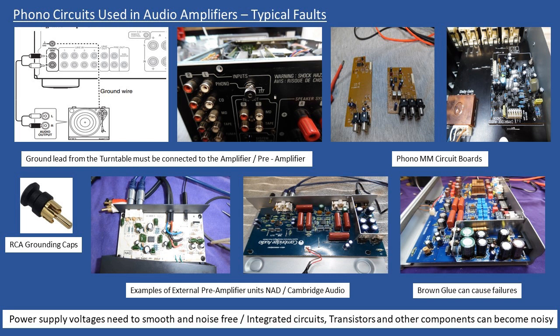And then if it's none of those faults, you have this sort of crackling sound, then you're normally looking at a component which has gone noisy. And as we mentioned, it could be a transistor, it could be a capacitor, it could be a diode, it could be one of these integrated circuits. For the many years that I've been repairing equipment, I'd say for phono preamplifiers, the most common faults tend to be the ones where they have the dual op amps. That's my experience. I've probably fixed more phono preamps with that type of fault, where they just go electrically noisy.